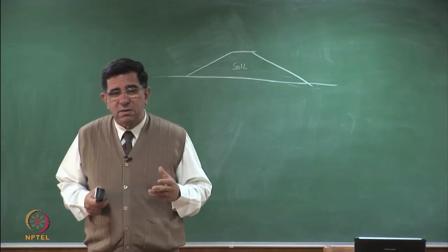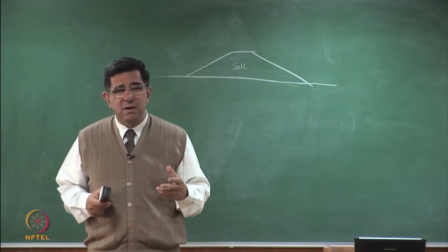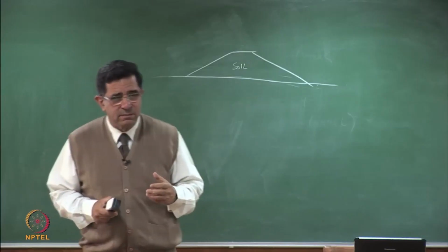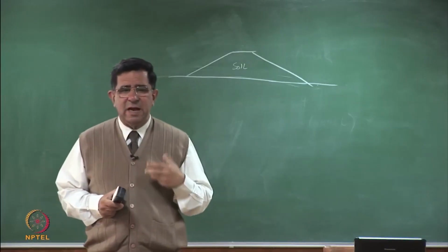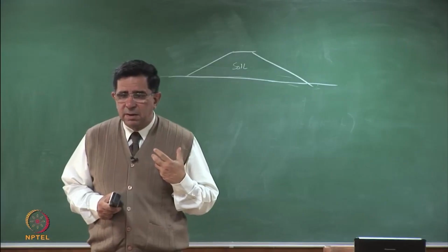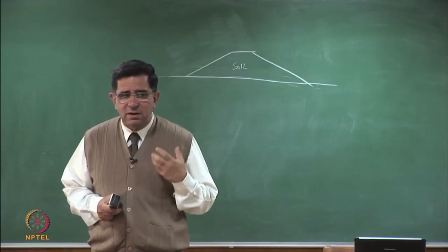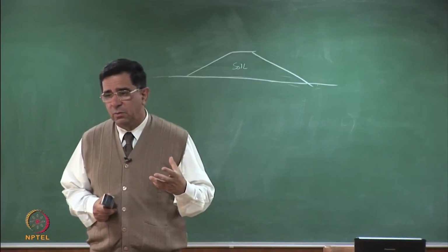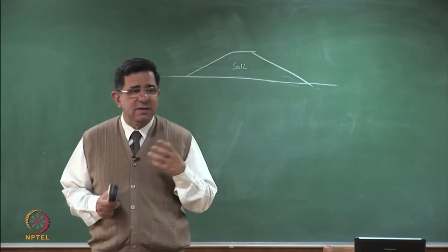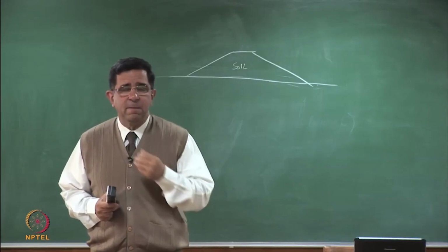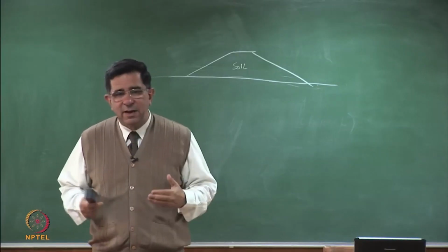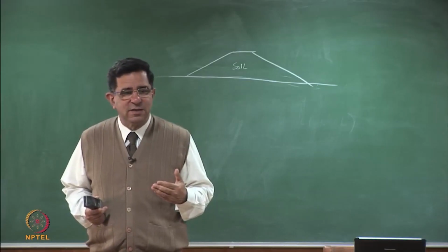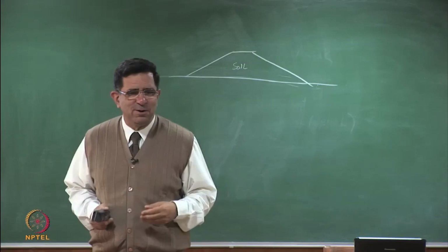Do you think this waste is going to behave like an undrained material or a drained material? What's your intuitive gut feeling? Yeah, so the tendency is that there are no net negative charges and double layers and low permeability in waste. So it is basically drained parameters. Again, let's look at gut feeling. What are the parameters that we are taking out if we are doing drained direct shear tests? What size of the direct shear box would you like to adopt?